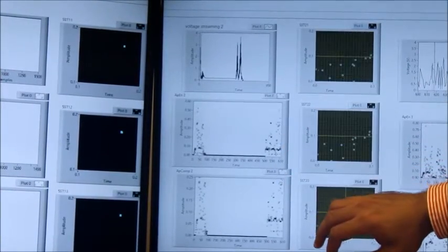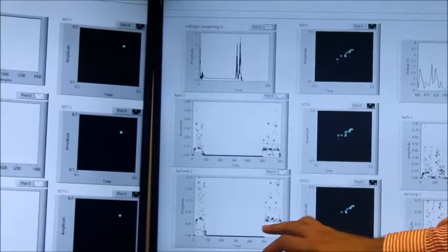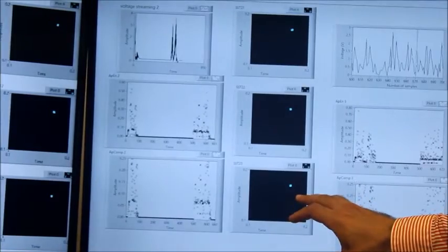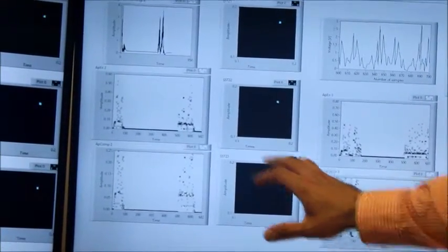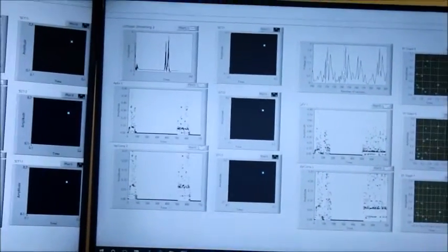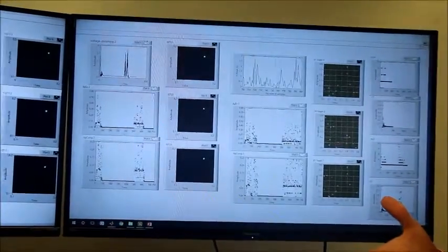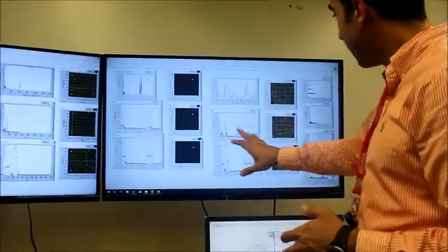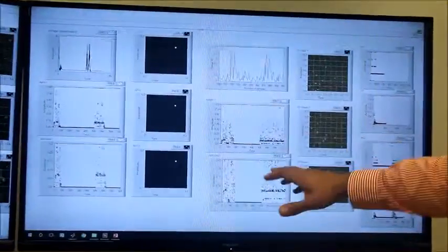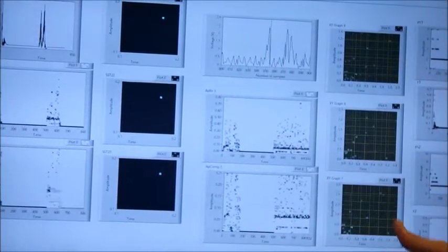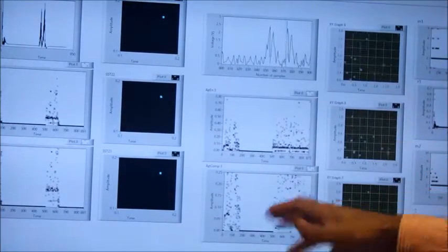You can see both entropy and complexity are increasing here, and the phase space over here, after the fault is cleared, goes back to 1 single point, as we expect for the phase space of the normal system. And here the system goes to the islanding condition. You can see after the 500, at which the system goes to the islanding condition, both entropy and complexity increase.